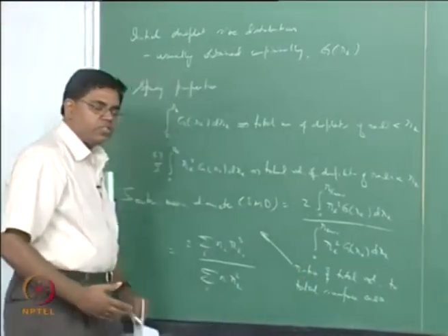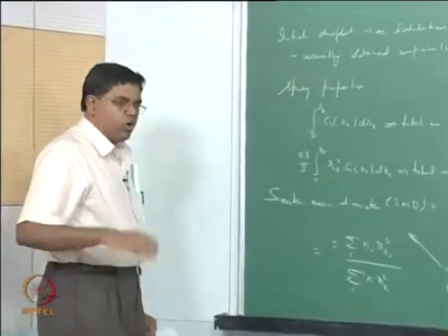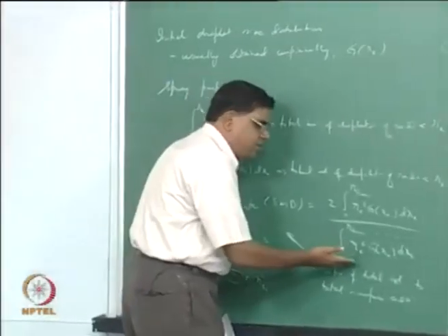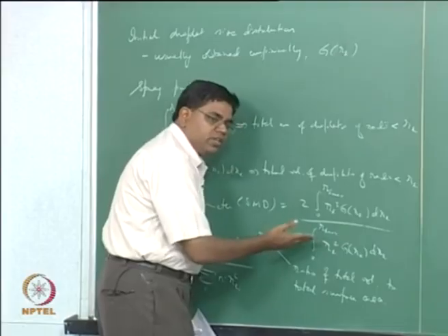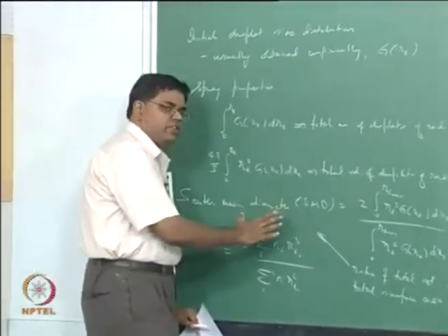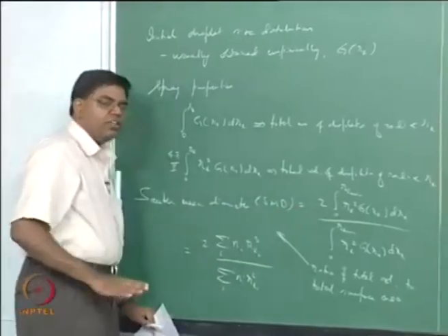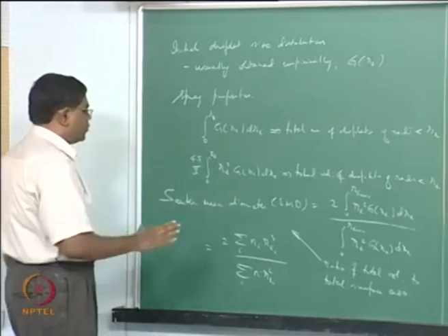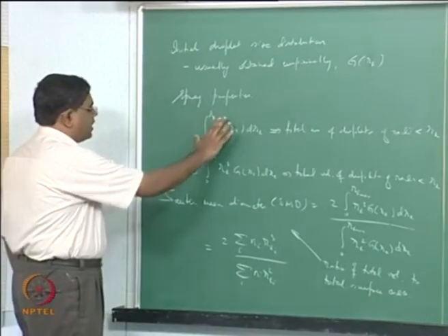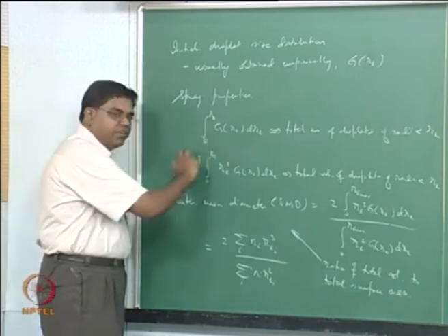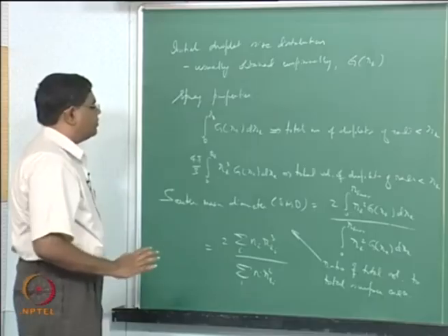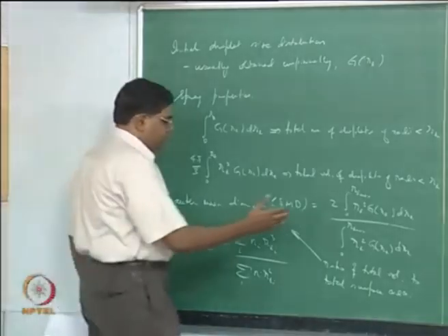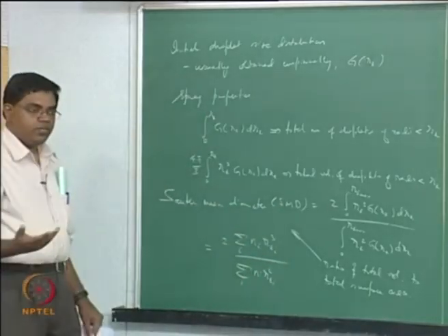Okay, so if you now have a larger and larger atomization done, of course the volume corresponding to it is also preserved. So typically if you have the same radius for all droplets, then it doesn't matter; you will get the same mean radius regardless of how you averaged. You did an arithmetic average, let's say, so for example this is the total number of droplets, and then you have the integral 0 to RL max of RL G(RL) dRL divided by the integral 0 to RL max of G(RL) dRL. That would be the arithmetic mean, and this would be the sort of mean diameter. You could also have a weighted mean diameter and so on.